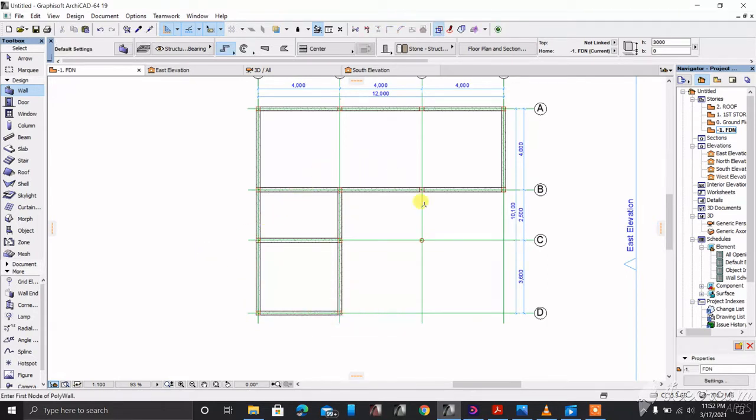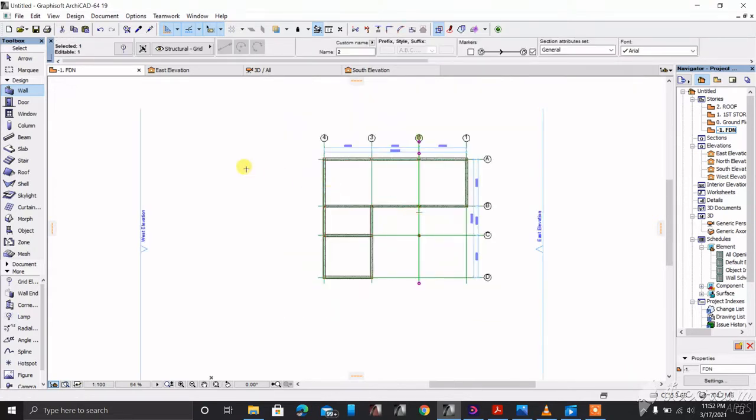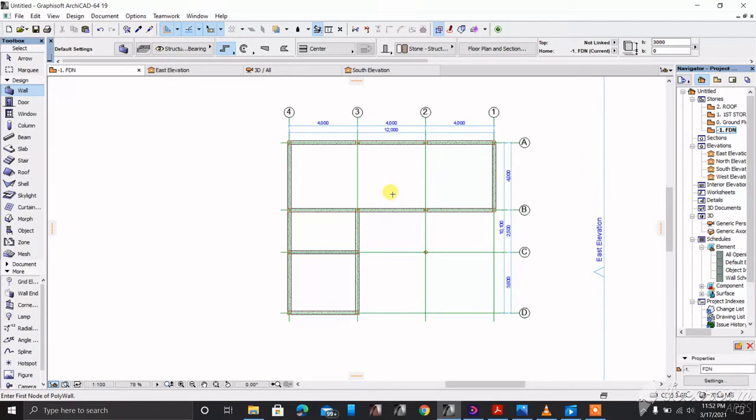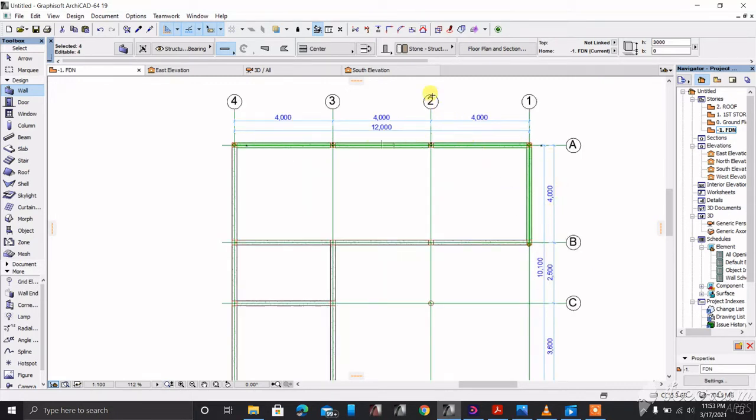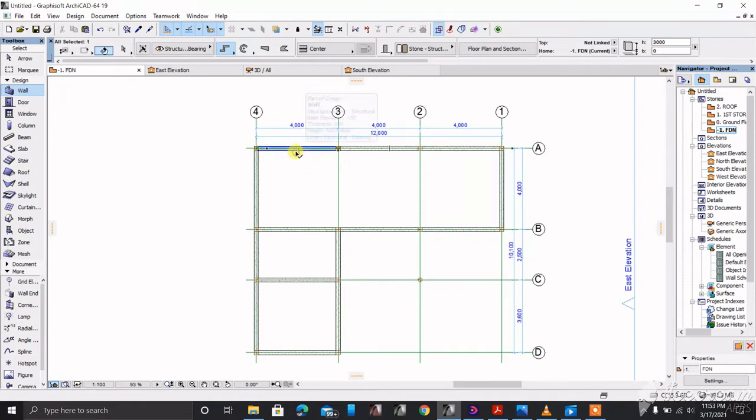When you click your walls and everything is suspended, like for example, if I click my grid elements, they're grouped, so you need to suspend them in order to use them, like for example this one. So all these walls are suspended, so we're gonna unsuspend them for us to be able to click each of them.